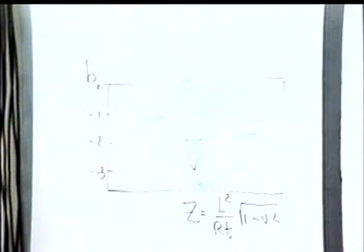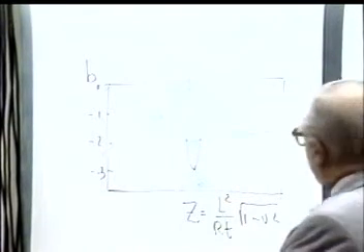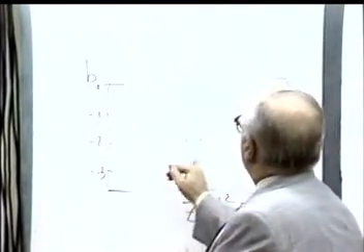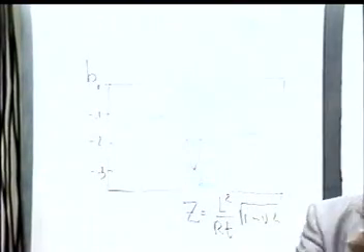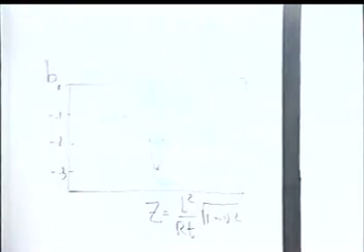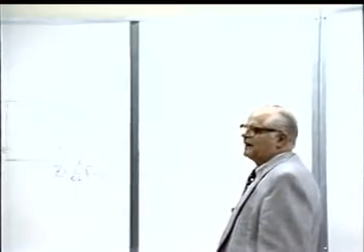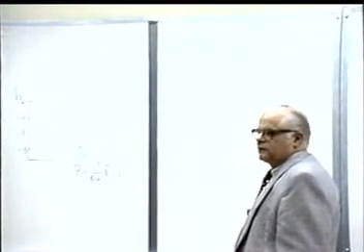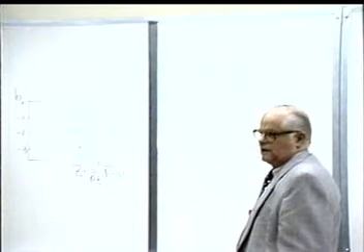Well, may you repeat the question? Yeah, the question was whether we could vary the length such that the two eigenvalues will precisely fall on top of each other and thereby establish a critical length. I think that certainly when the paper is written it will be one of the conclusions, that if you design a shell, you will have to make an investigation. Are there any lengths where you will have the occurrence of nearly simultaneous modes?